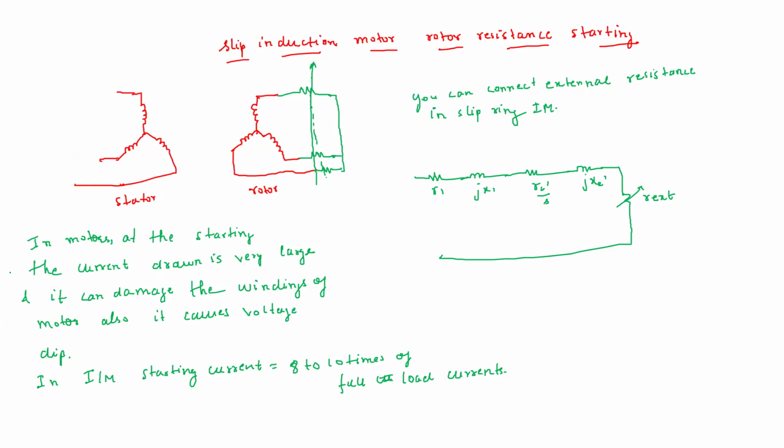So for other loads there will be under voltage conditions when the motor is starting. If the motor has to continuously start and stop, then whenever the motor is starting, it will continuously draw huge current. So it will impact the efficiency of the other components connected in that phase. That is why you need to have starting methods.